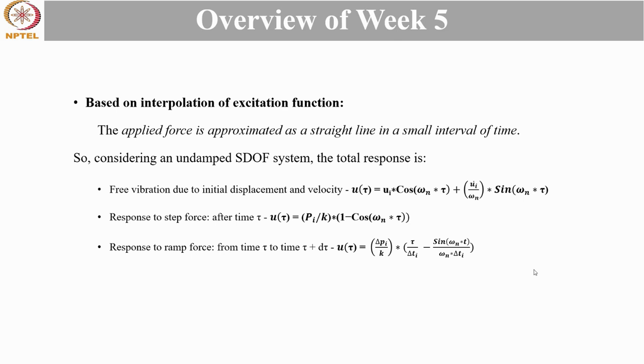So individually we can calculate the response due to the three conditions. After estimating, the total response at a particular time step will be the sum of all these three responses. And after estimating at a particular time step, the total response can be seen as a function of time just by recalculating the initial condition and force applied before each time step.